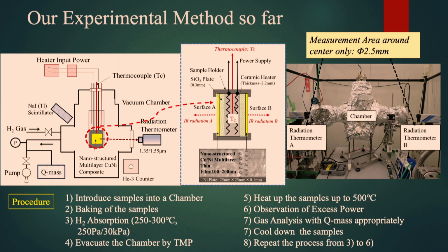In our experimental method so far, we measure the temperature in the center of the ceramic heater by thermocouple, and we also measure the surface temperature by two radiation thermometers. But with this method, the measurement area around the center is small, about 2.5 millimeters.